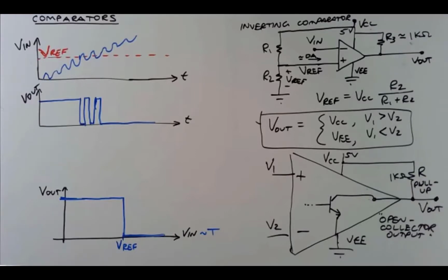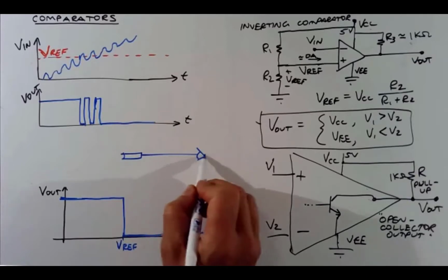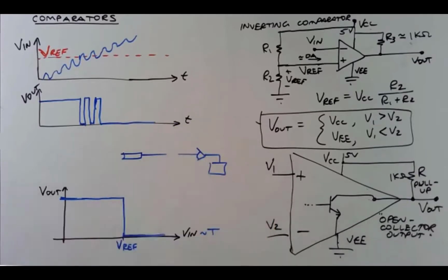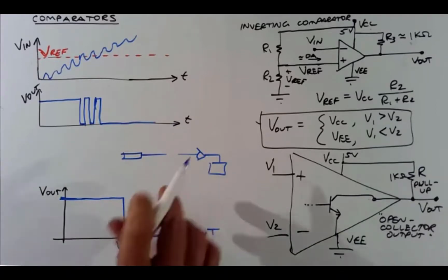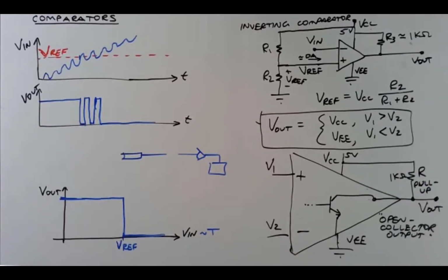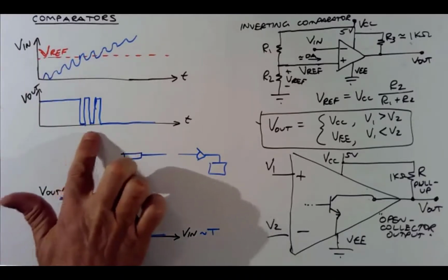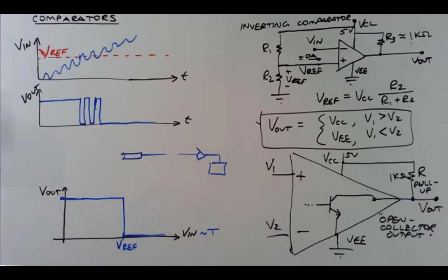Let's say you were building a comparator that compares light intensity from a sensor, from a laser that's meant to count people. In other words, you might have a laser, right, and then a light detector and a comparator. And so when someone breaks the beam, the count goes up, right? For each time someone breaks the beam, maybe each falling edge, the count goes up. Well, if you have many transitions, you count the edges. You would actually count, what, like 3 people crossing through this beam if you had a little noise on your sensor voltage.